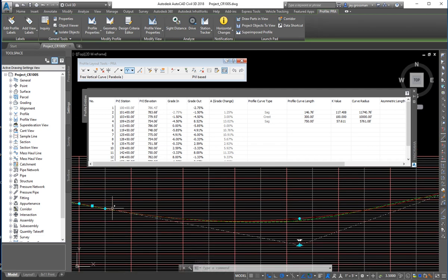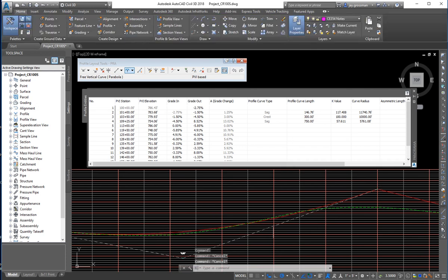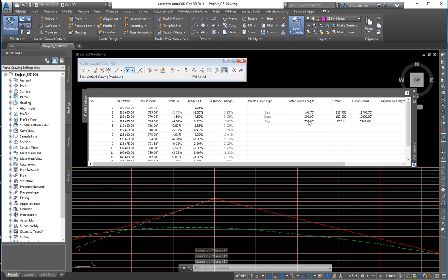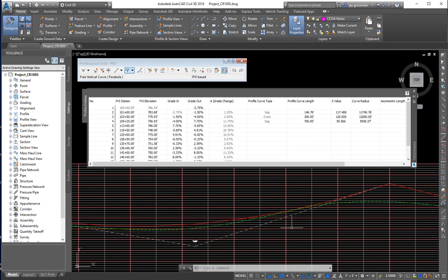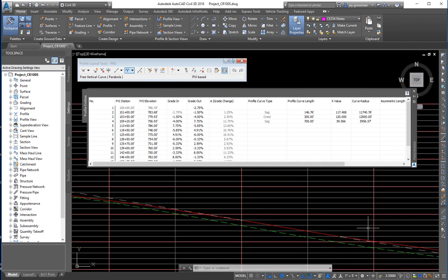Yeah. See, here's one PVI. Here's the next one way up there. All right. So something isn't working here. We may have to rework this guy. Yep, not going to work. All right, so we just have to bring this up. We're just going to have to put in a big section of fill. Let's try -4. Right, and then let's drop this down. Let's go back 700. All right, now this is the end of my curve. It's still way too high to get that through there. Yeah, we're just going to have to be a little bit higher through there.